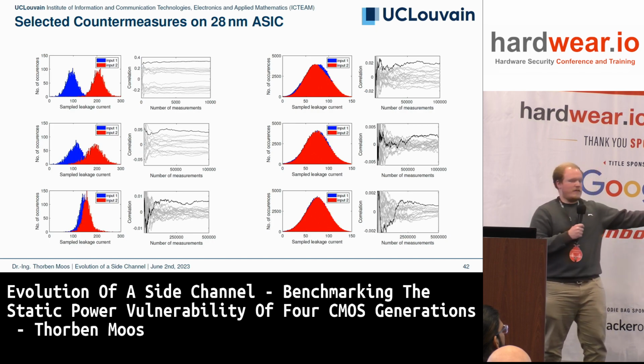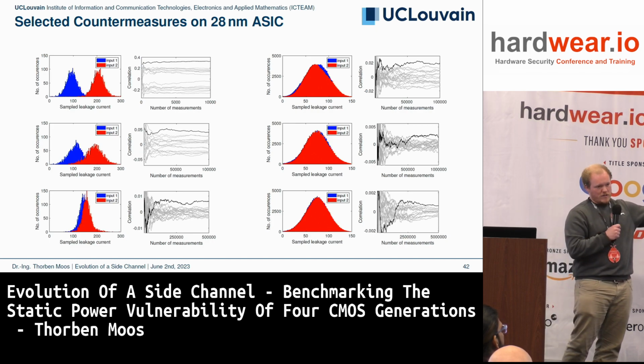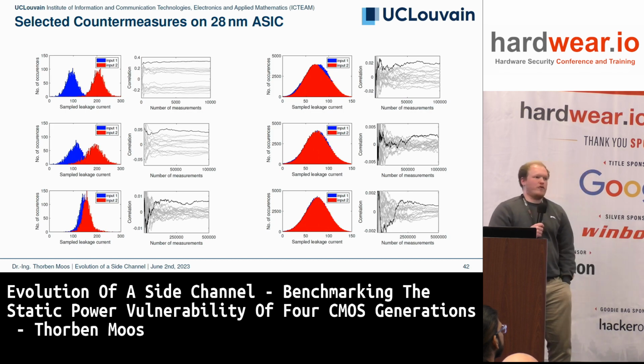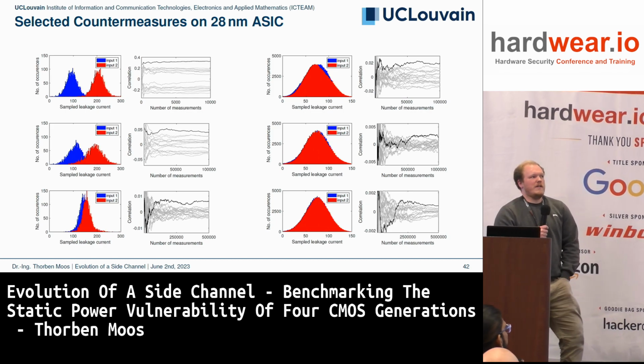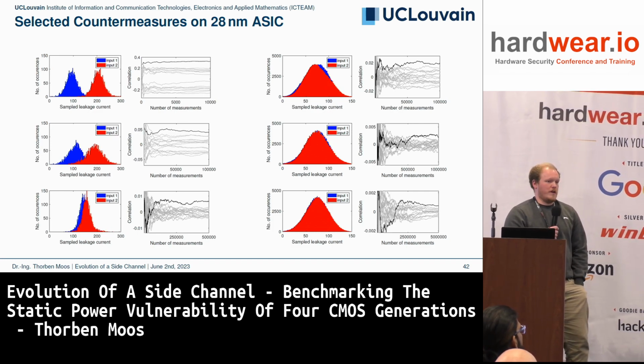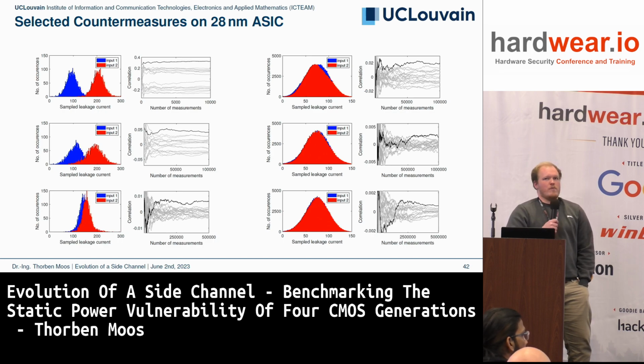So that's kind of leakage model independent. We have also used template attacks, and of course, the more your leakage model deviates from a simple bit model or Hamming weight model, the more it helps. So template attacks are definitely usually the better solution to argue about the security of the implementation.